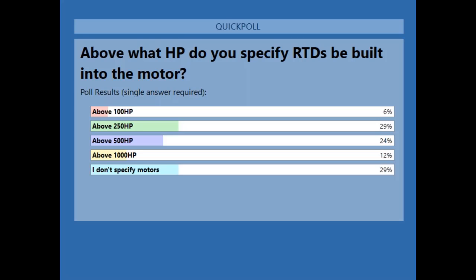And if you're going to specify RTDs, the most common today is 100 ohm platinum. Try and stay away from 10 ohm copper. The resistance in that wire that I was talking about can only be 25% of the total resistance. So if you have over 2.5 ohms resistance on a 10 ohm copper, it's not going to read right.